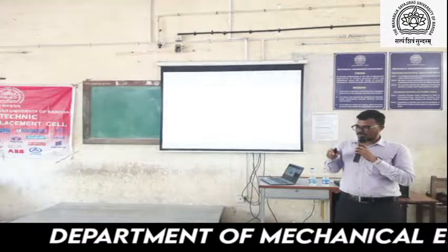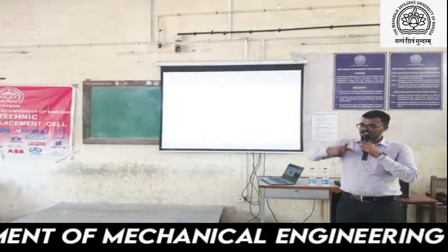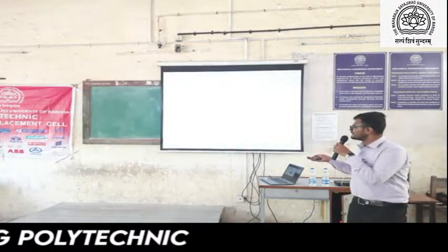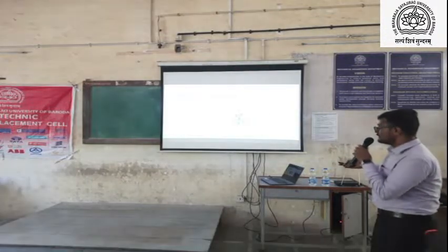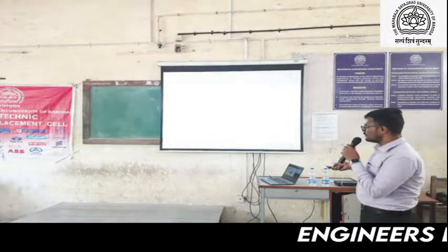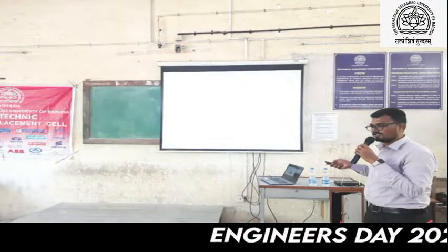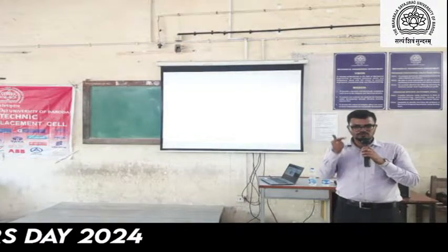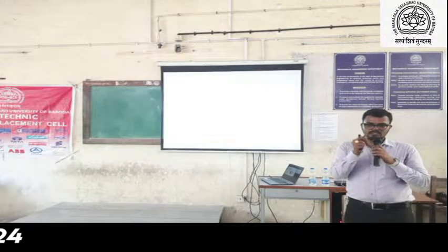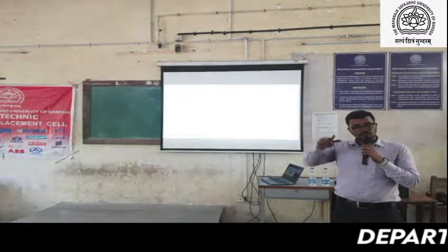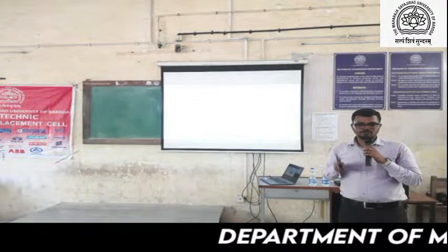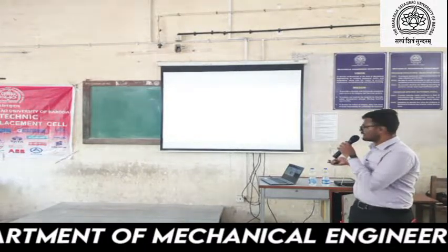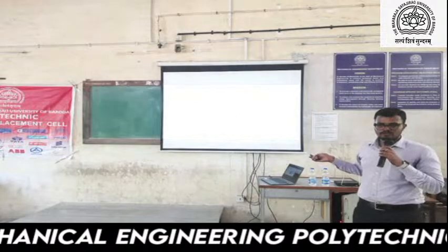In that cam profile you have drawn, unwinding the thread, something like that. So this is the involute profile. This is the cycloidal profile. This is also based on application. Involute profiles will be used in major applications, 98% of gears will be manufactured through it. Daily it is rotating continuously. So each day, if it is rotating with an efficiency loss of 1%, think about the loss. So in that kind of high precision, accuracy application, this cycloidal profile will be used. Am I right?